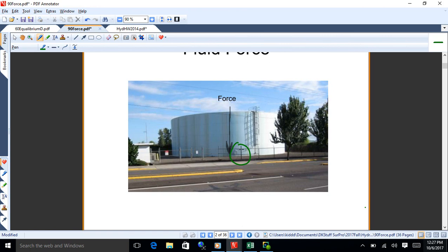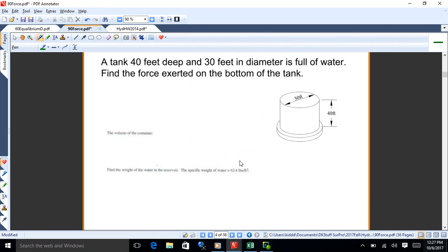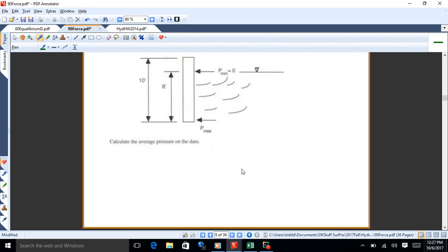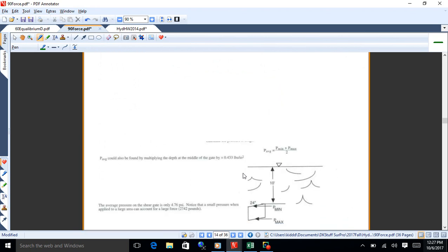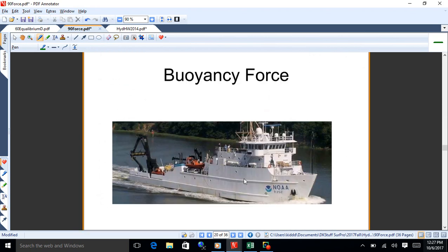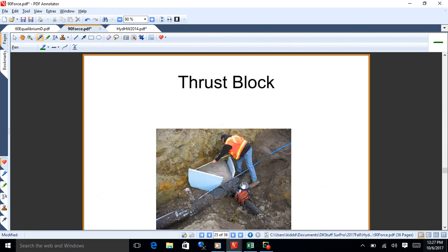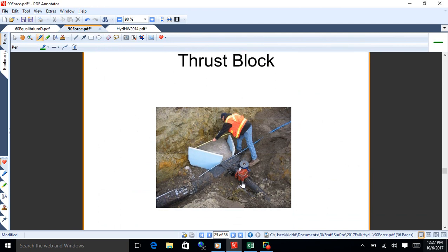You know, when you build pipes, you use thrust blocks to absorb force. And I've heard a few stories of people neglecting to do these things and running into some problems. That's a thrust block there, just a big old chunk of concrete that helps hold that water T in place. Because when you have an unbalanced situation like that, like instead of a cross, you got a T, you're going to build up pressure that way.